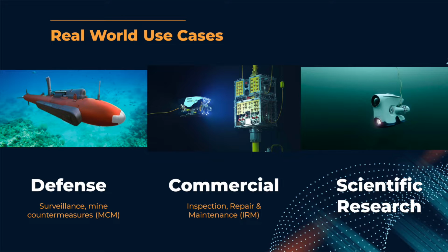If you look at who actually uses underwater technologies, robotics or communication, the same question that I was asking 12 or 15 years back, there are two or three major segments. Obviously there is a defense segment, which uses it for applications like surveillance and mine countermeasures. These tend to be longer, torpedo-shaped AUVs, which can cover large areas but for survey kinds of applications. Then there is a commercial sector, which primarily uses ROVs because they need a lot more degrees of freedom, and not just inspection, they need intervention because they will have manipulators, they will have to turn knobs or pick up something. As compared to AUVs, the area of operation is typically smaller, but they need to do much more complicated tasks.